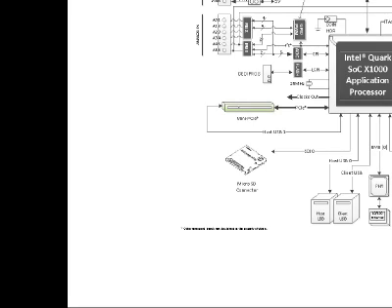This is a diagram of this Galileo board. As you can see, here's the Intel Quark SoC application processor. It has a lot of connections to peripheral interfaces going from here. This is to the DDR memory, and it has a JTAG debug interface. It connects to this mux, which in turn connects to a socket interface, where we can find this I2C and also GPIO pins.